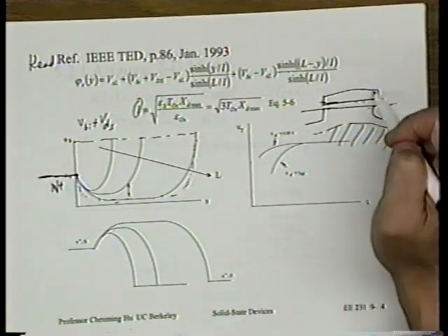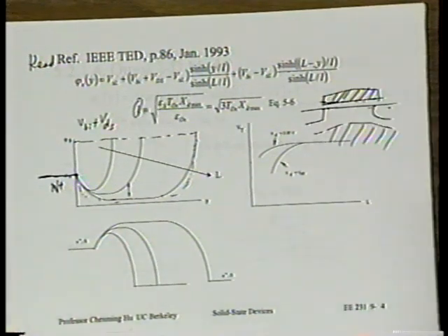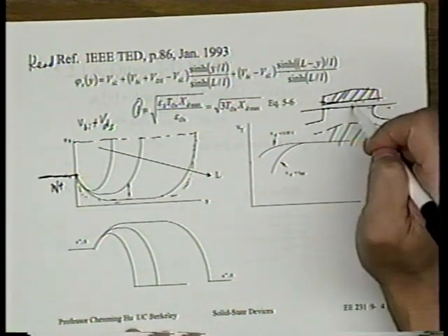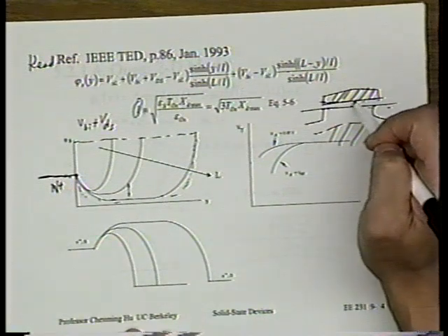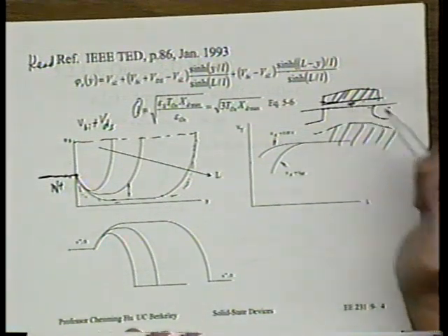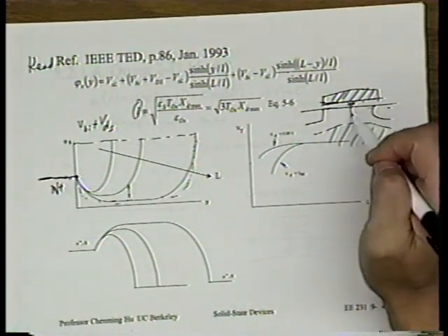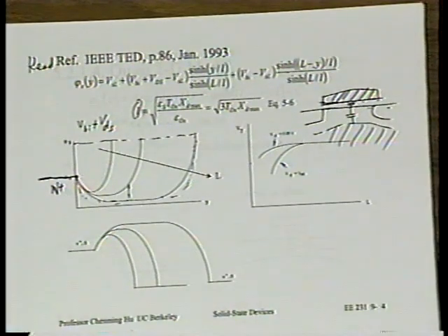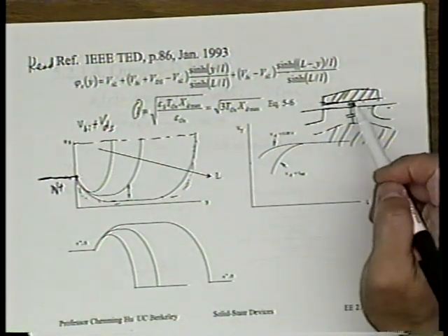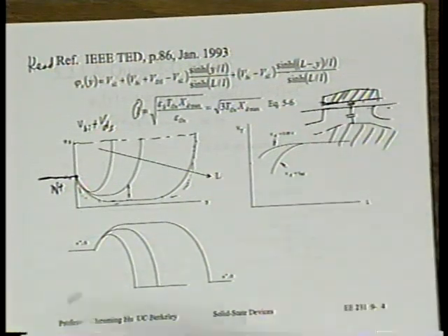This back gate and front gate are very similar in many ways. Both of them are coupled to the channel, just through two different capacitances. One through the gate oxide, that's Cox, and smaller is better, we already know why. And the other gate couples to the channel through another capacitance, another dielectric thickness. If thinner Tox is better, shouldn't smaller xd max be better?